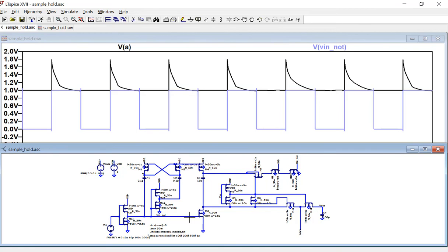Whenever I'm turning this on, I need a high voltage at the gate of this NMOS to be ready. So here, this pin is called VE0, which is the blue one. And this voltage is called VA, being labeled over here. So this is VA, which is the gate voltage of this transistor. And here's VA. Are they high at the same time? Remember, whenever I want to turn on this NMOS, I'm pulling this down and I want to turn this on so I can transfer VDD over to this point. So it needs this gate voltage to be high. Are they high at the same time?